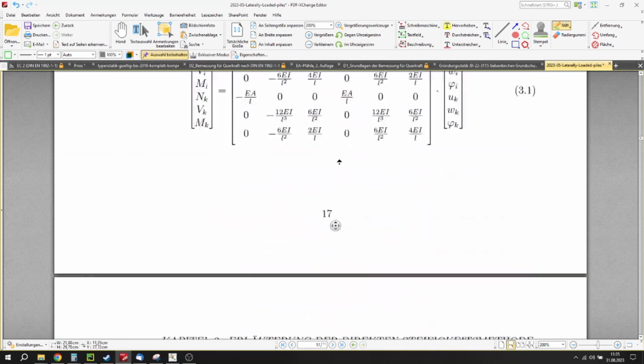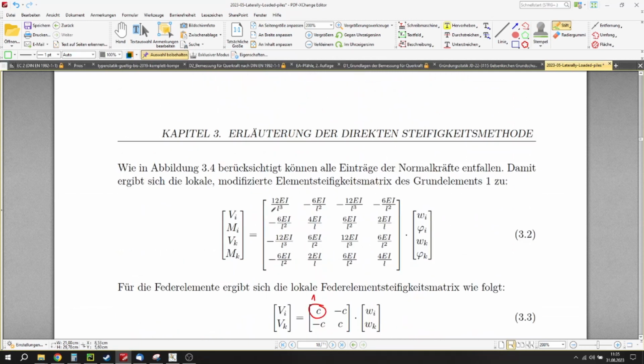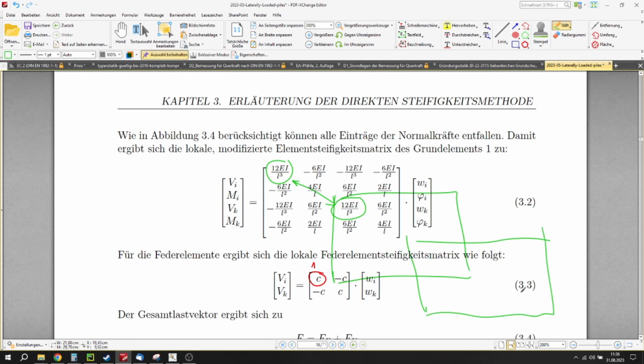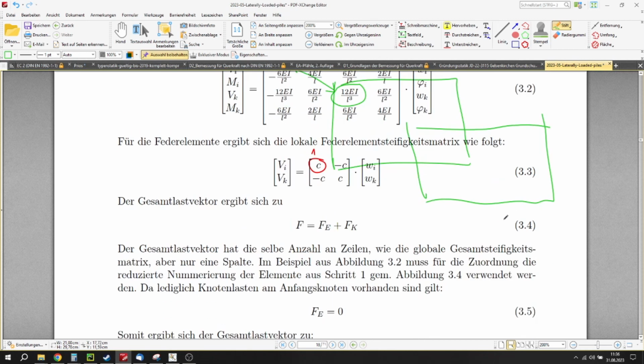So the way that this works is we go here into the stiffness matrix for our first element, and we take this one and we add this to the 33 entry of the second element. And since both of these base elements have the same stiffness matrices, we can just add these two together. And what you see now, and this is really cool and really handy, is that these basically are the same entry. So if you align these in this fashion, basically you have very strong symmetry effects.